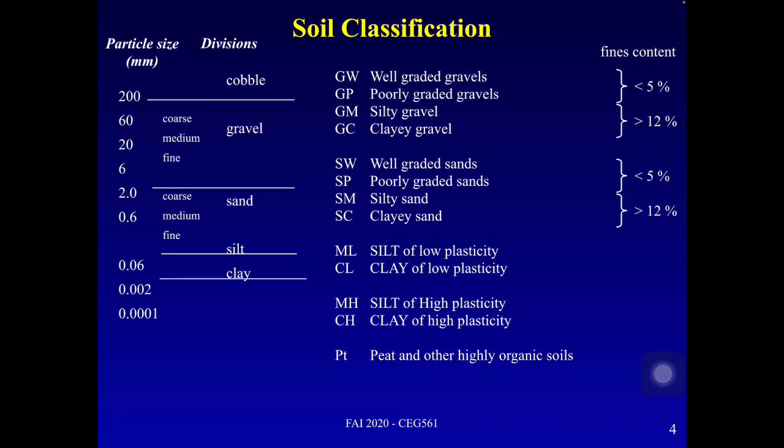Okay, this slide shows the soil classification based on British Standard BS. What is special about British Standard BS is that you can see here, the number is the magic number, what we call the magic number, 2, 6, 20, 60, 200, 600, 2000. So always remember this magic number.